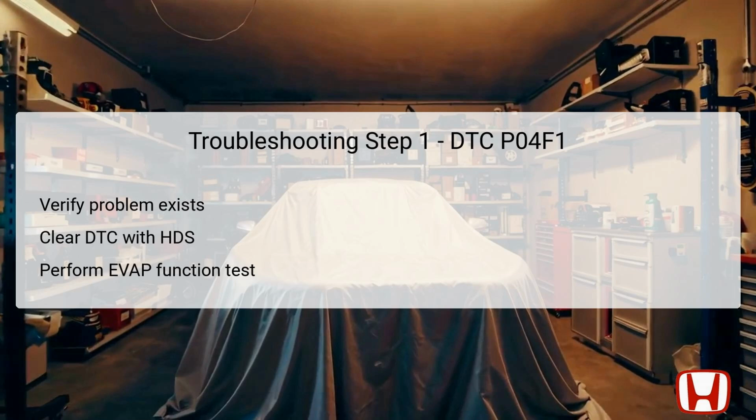This test checks the operational condition of the EVAP system components. If the test results indicate that the system is functioning properly, this may point to an intermittent failure, implying that connections or terminals could be loose or damaged. In such cases, investigating the wiring harness connector for the FTP sensor, the EVAP canister purge valve, the EVAP canister vent shut valve, and the powertrain control module (PCM) becomes a critical follow-up action.